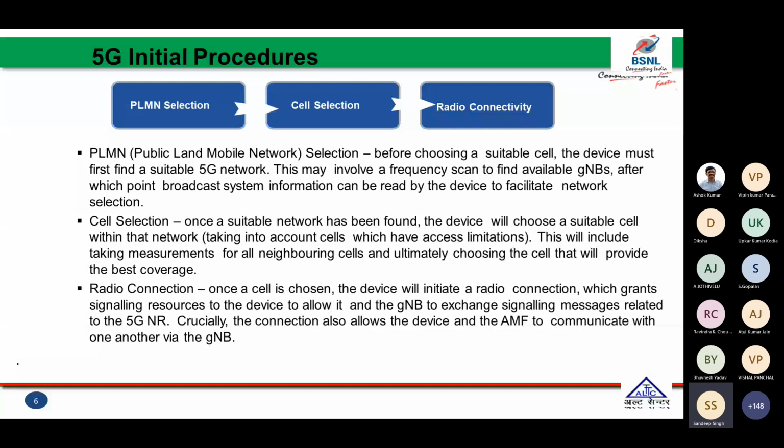The difference between the received RSRP and the minimum is the criteria for cell selection, defined in the SIB1 message that is broadcast by the gNodeB to the UE. They compare both. If they are greater than 0, then cell selection happens, otherwise cell selection will not happen. And this criteria is very similar to 4G, and also very similar to 3G.